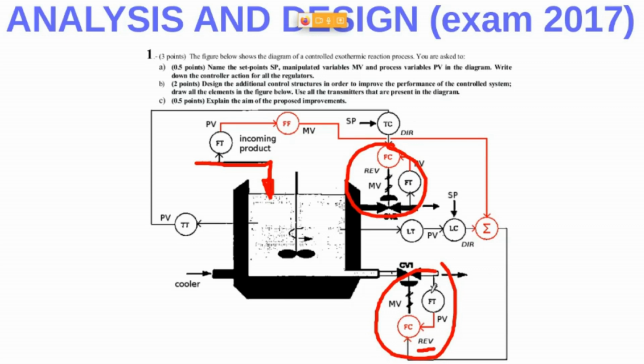Opening of the valve implies the increasing of the flow rate, right? Well, here this level controller is configured in a direct action because the valve is for emptying the tank. The valve is at the output. Remember, if you open the valve, if you increase the controller action, the level in the tank will decrease. So that's why here a direct controller action, right?